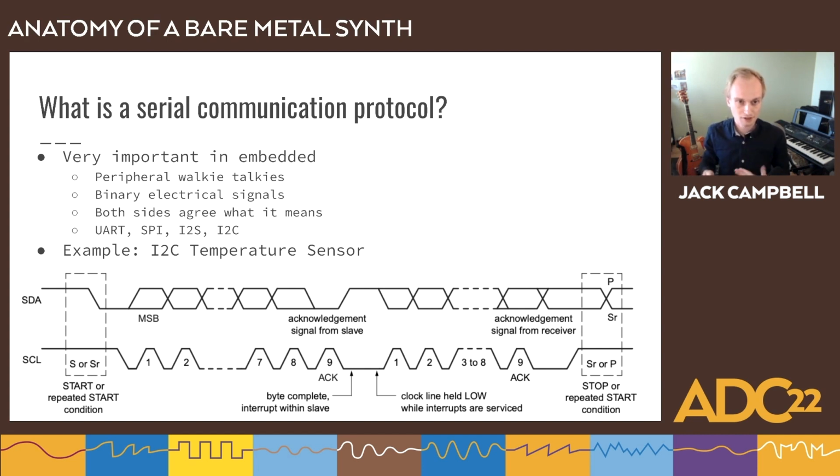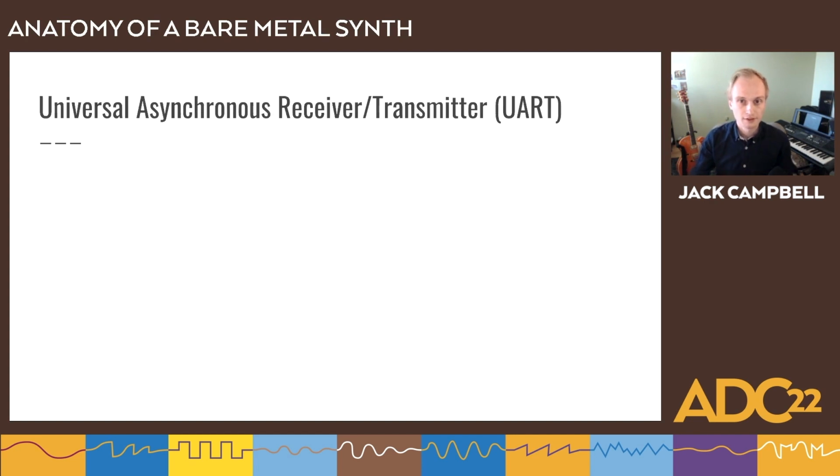And then there's a clock line under it, which is important for these kind of synchronous protocols, because the data line might be sent at a different rate, might not necessarily be stable. So the receiving end needs to know if it gets a big long 0, was there just some sort of issue that made that bit extra long, or is it actually supposed to be 2 zeros in a row? And so the clock line says, read a bit now, and now read another bit, now another bit. And so it can keep the receiving end in sync like that.